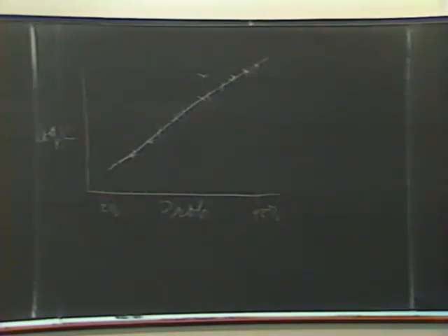So getting the boundary conditions, that is the inputs to the system, is difficult. I might mention another one, and that's San Francisco Bay, the loss to the ocean. You know, that's a boundary condition. How much sediment is lost to the ocean? That's a difficult problem. What we're doing now, and I've done in the past, is to make a sediment balance.